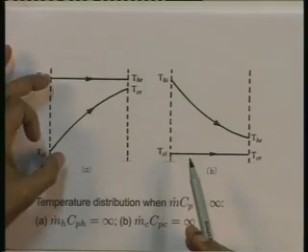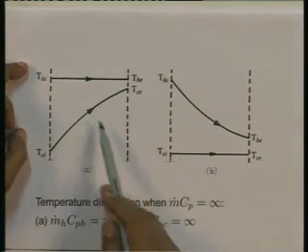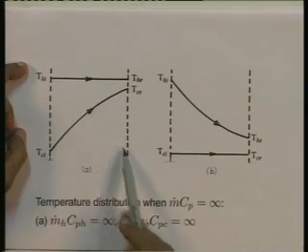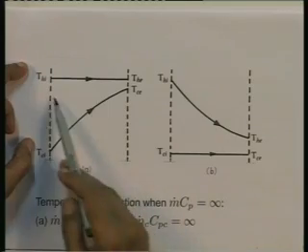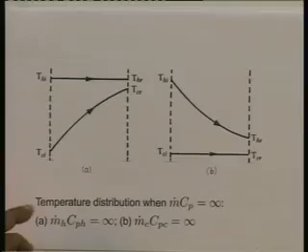The way I have shown it, it is parallel flow, but remember, even if it is counter flow, all that will happen is I will get a mirror image kind of variation of T c in the other direction, and therefore, you can see why the mean temperature difference is the same whether it is counter flow, cross flow or parallel flow. So, these are the two special cases.